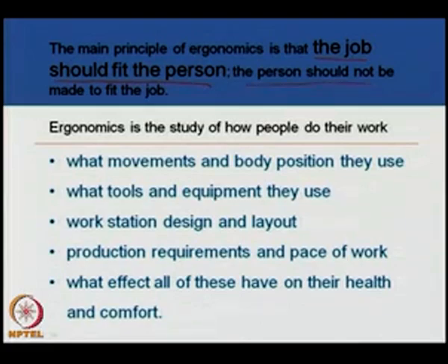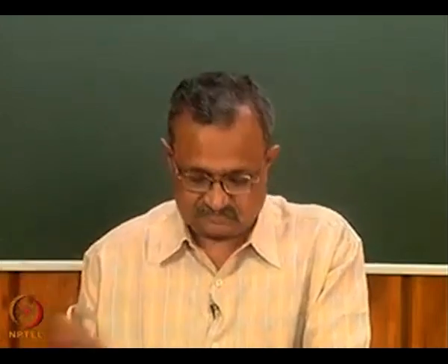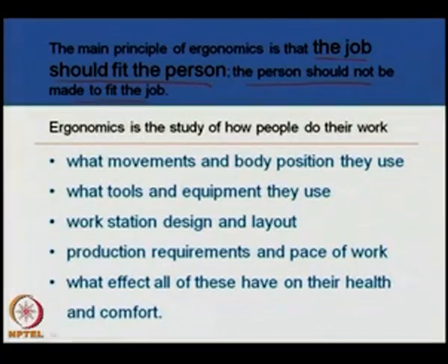The person should not be made to fit the job. Means the man is the prime system component; consider his requirements first and accordingly devise the others. Ergonomics is the study of how people do their work: what movements and body positions they use, what tools and equipment they use, workstation design and layout, production requirements and pace of work, and what effect all of these have on their health and comfort.